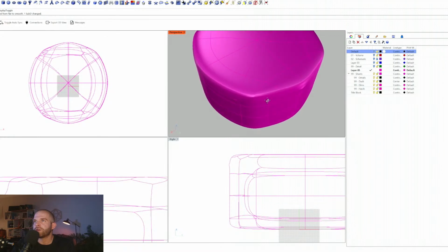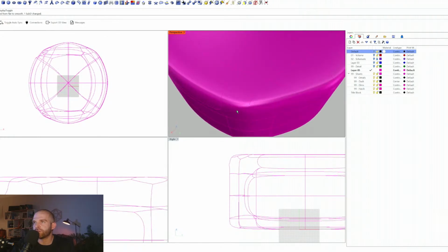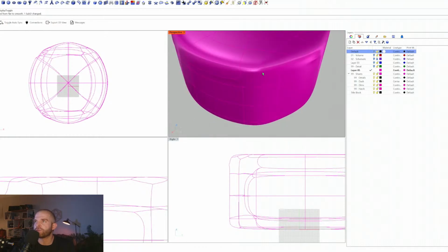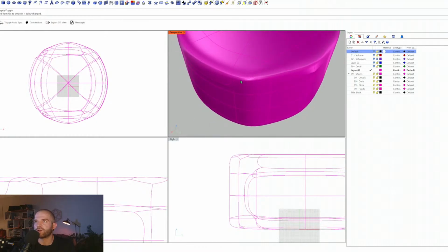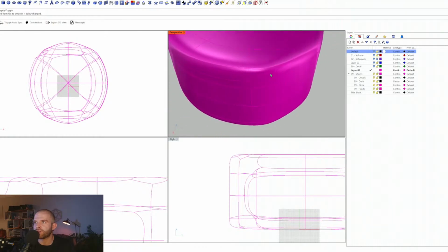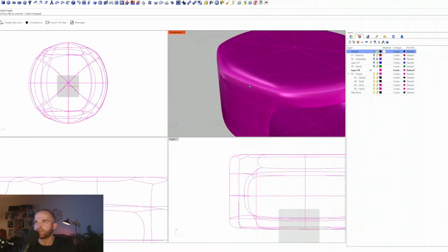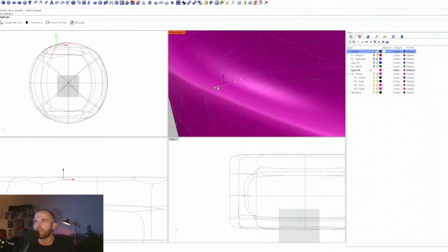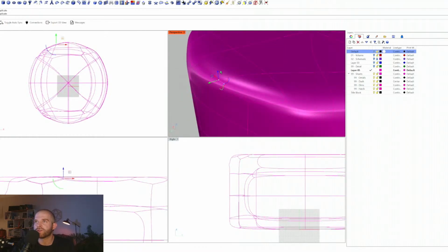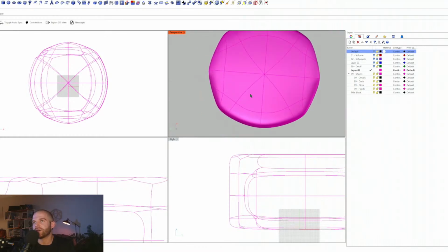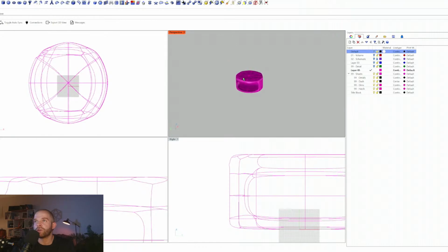So what's happening here is wherever we have an intersection, like too many curves or too many points connecting, and there's no curve here to infer that, we're getting these harder edges, which makes sense. Wherever you get a more concentration of curves, you're gonna get more defined edges. So the spacing here is what's doing that, and not having a smooth line right here. It'd be very tedious to start doing this. So for perfect shapes, definitely better to start with NURBS.